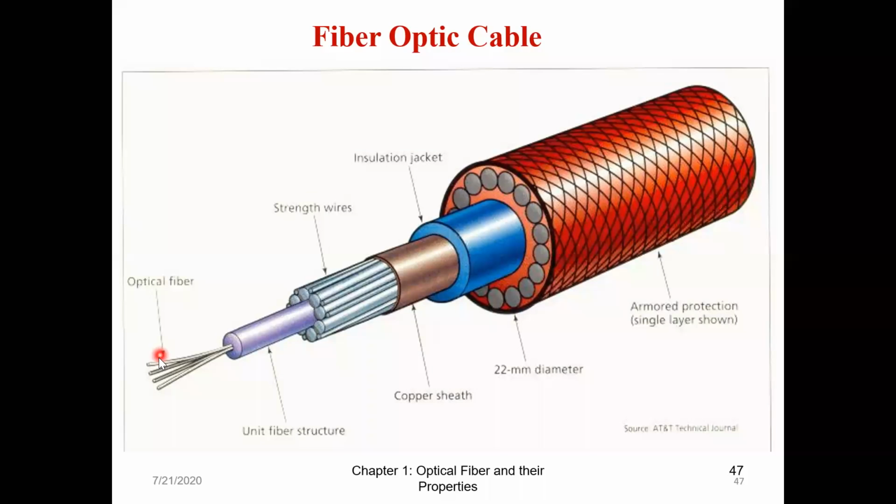Now when I am joining a fiber, if there is a cut in a particular fiber, I will come to know. If this is an orange color, I will join it with an orange color only. I will not join it with a white color, because every fiber is carrying data of some particular channel. To identify which fiber is cut and to join the appropriate one, I will join orange with orange, white with white, green with green.